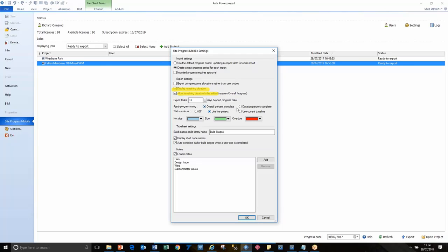Also I'm making a decision whether I should use a duration percent complete or an overall percent. And we always recommend the overall percent because you can change the remaining duration. It doesn't affect the duration, etc. And there's a color coding system that you can use. You don't have to give people clues to the status of the activities that you're presenting to them, but I like to do that.